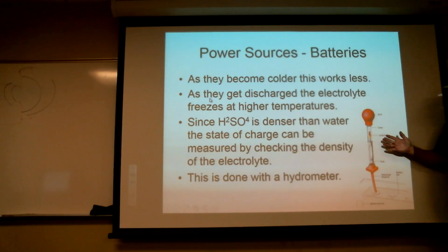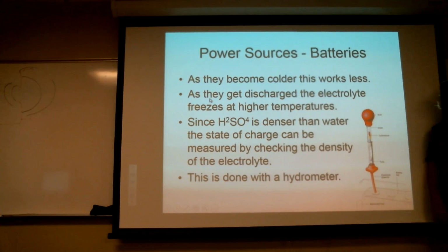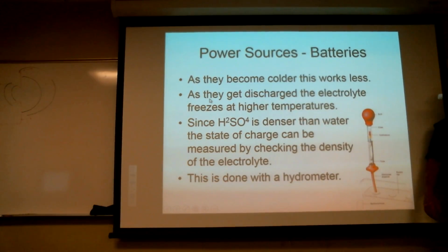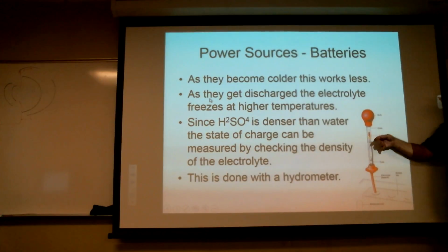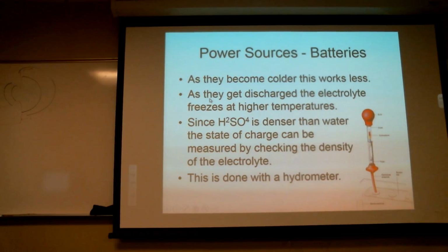So what we're really trying to verify in a practical sense is, is the battery charged? I'm in the green, it's probably charged. Check each cell. I'm sort of in the middle down here, throw it on the charger for 12 hours, come back. Did it charge? It's not charging, battery's a problem. Okay?